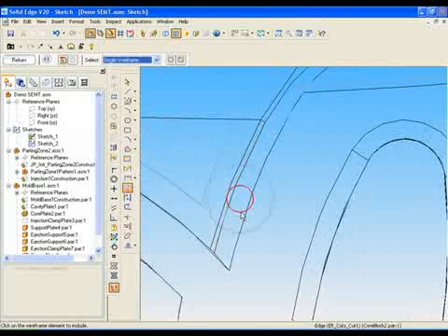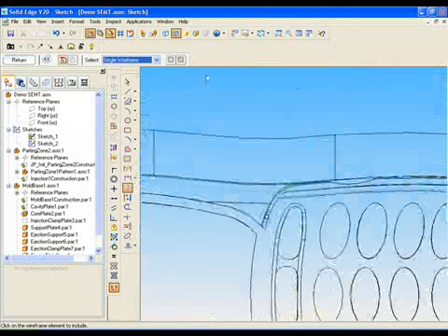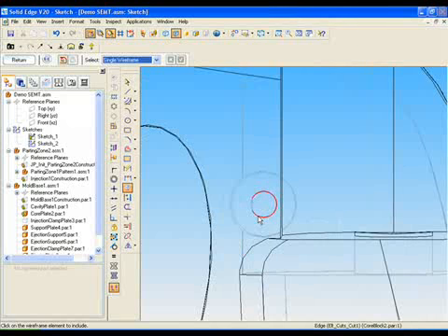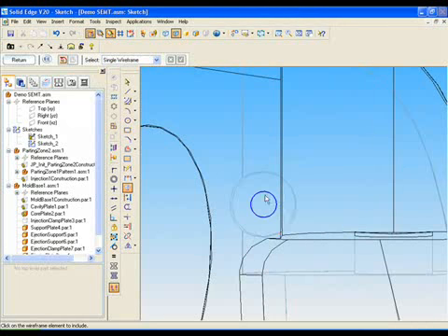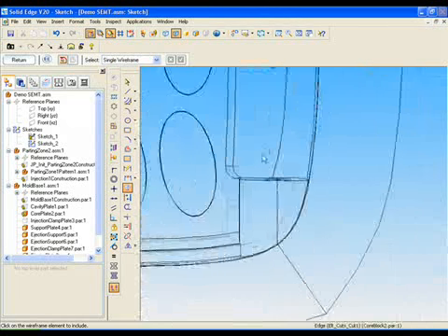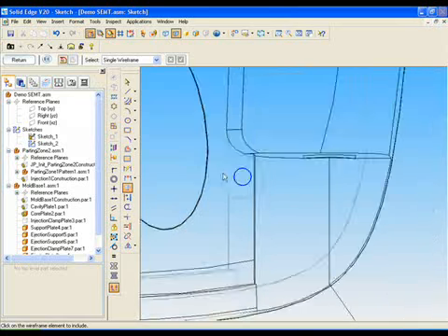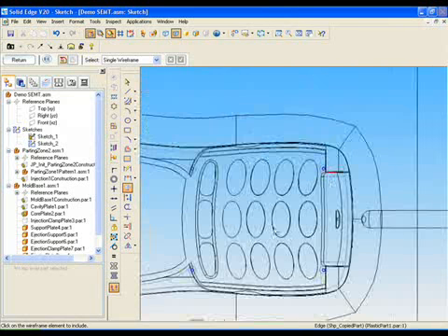The circles in the sketches define the X and Y position, but the Z level is not defined by the sketch's plane. The Z level is set by selecting a face, a plane, or, as it is the case for ejector pins, is defined automatically to use the correct face of the ejector plate on the mold base.